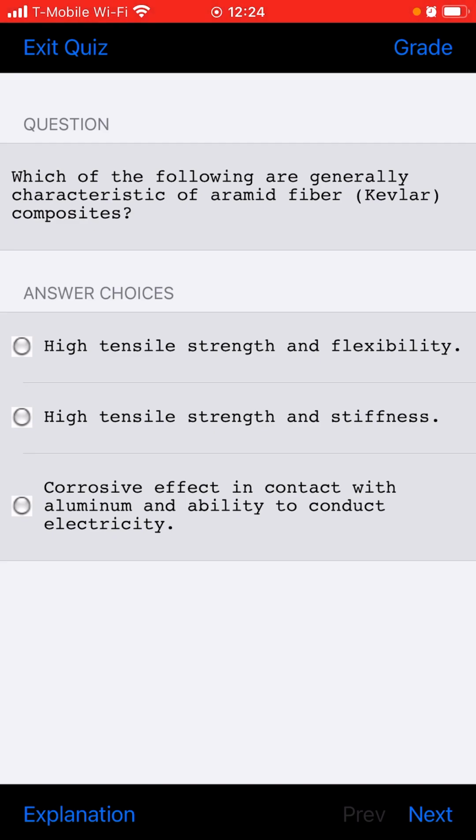When making repairs to fiberglass, cleaning the area to be repaired is essential for a good bond. The final cleaning should be made using MEK, methyl ethyl ketone. When it comes to fiberglass, use MEK, baby.